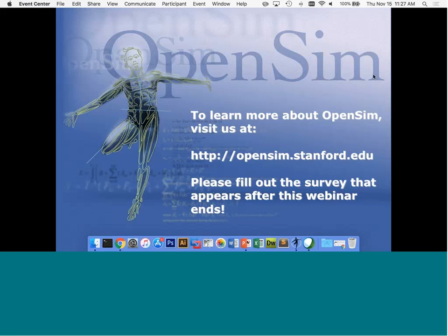Okay, so another question from Arash Ganabadi. In MATLAB scripting, how can we visualize the model during IK? You can. You have to turn the visualizer on. So the model has an option to have an accompanying visualizer, and that by default is false.